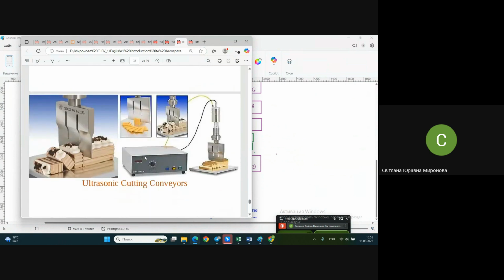Ultrasonic cutting. It's maybe ultrasonic cutting and ultrasonic welding. And what is the idea of this cutting? This tool will move in the direction of cutting. It just moves, but together with it, it's trembling. It oscillates in the normal direction with very high frequency, higher than we may hear. But literally, we may hear it, and it's a very ugly sound, I would say.